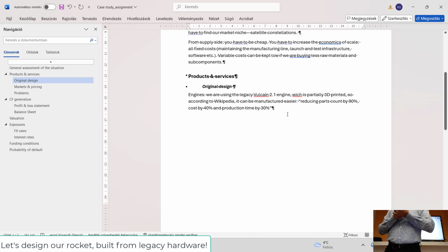Because the problem is that if you are using screws to put things together, then you need some kind of sealing between the two components, so it can fail. Also, the screws can come loose, or you need special torquing equipment. If you are joining with rivets, then it can also break.